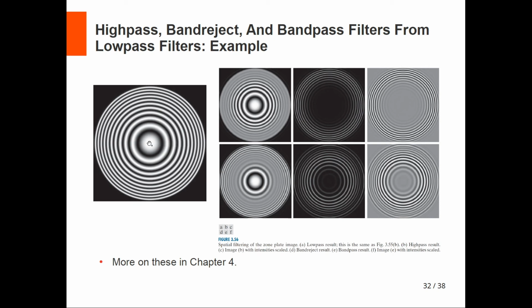As you go from the center to the end, these distances become smaller. So in the frequency domain, that means that we have several components of different frequencies. Here what we have is the result of low pass filtering. Any frequency that is higher than some cutoff frequency is smoothed, while the lower frequencies are kept intact.